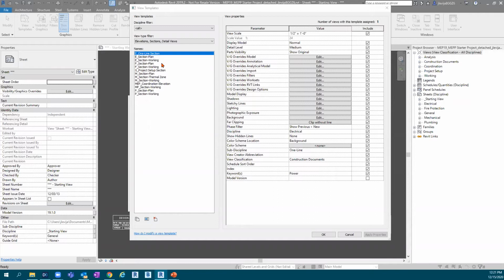We talk about section management whenever I'm doing training. That's just because I've been on projects where we had like 300 sections that have been pulled. None of them have names, and we don't know what's going on a sheet, what's not. So I suggest definitely utilizing that section working for any of those sections you're pulling, just to do some working modeling aspects there. And that's for mechanical, electrical, and plumbing. That's how I look at that.